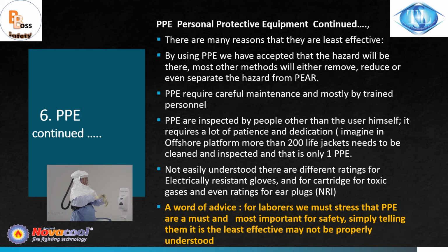So if I am in a refueling helicopter, and we have measured the noise in the refueling helicopter before, it was 120 decibel, and then the acceptable level in that company, let's say it's 85 decibel. Some companies are 80, but now we have 120, and that company accepts maximum 85 decibels. That's for 8 hours for 5 days.